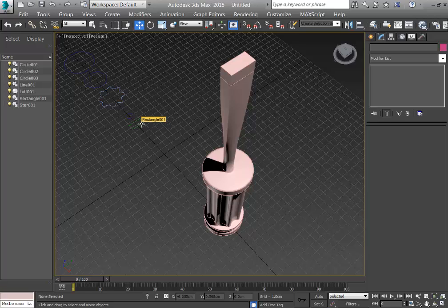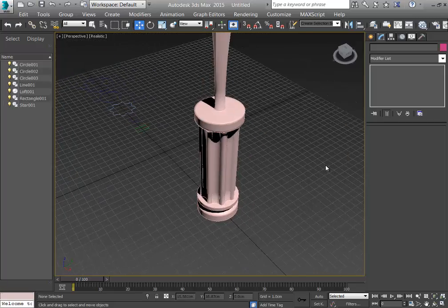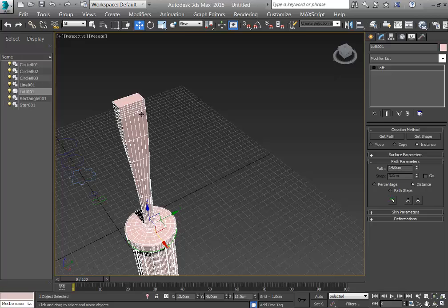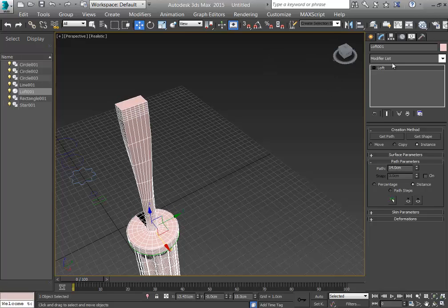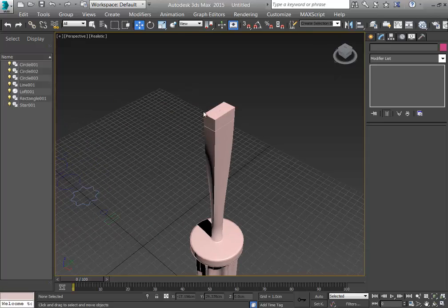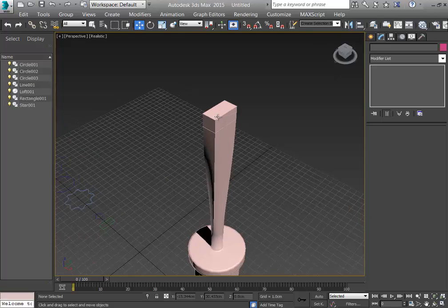Here you see that actual screwdrivers are supposed to start in a metal circle and goes as a metal circle till the tip. At the tip it should change the look, but here in our screwdriver, actually it is changing the shape from beginning till up in here, and that's not a proper look. So I click the loft tool now. From the modify section, I again just move the paths. By clicking this part, you can just move a green arrow in here. Can you see it there? Let me just zoom in so you will see that better in projector.